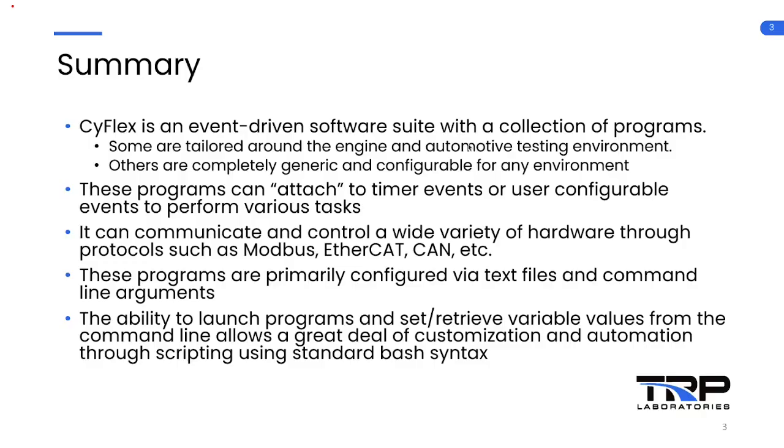using these event-based functions. So it can communicate and control a wide variety of hardware through protocols such as Modbus, EtherCAT, CAN, and quite a few others. We'll get into all of them later. These three are kind of the common ones that I see on most hardware I'm looking at.